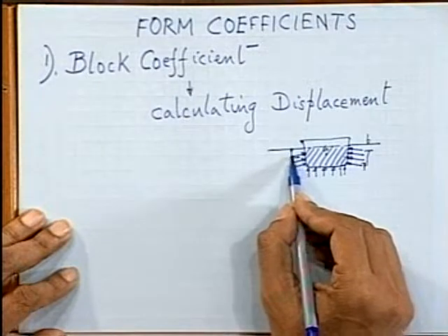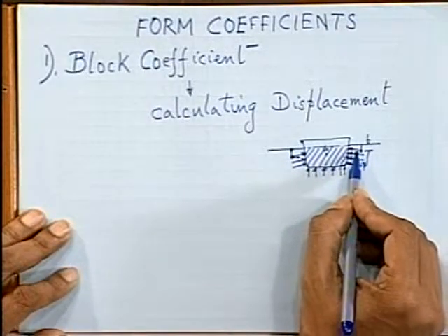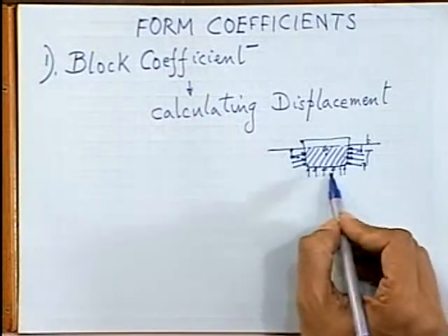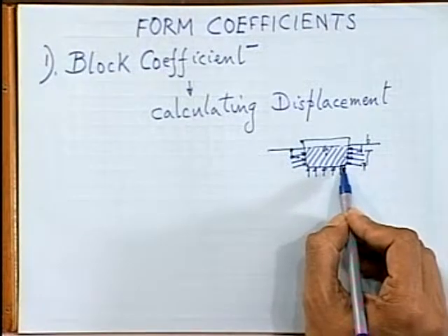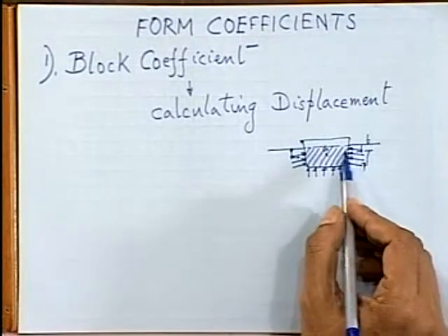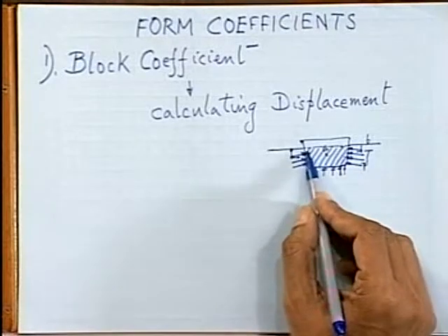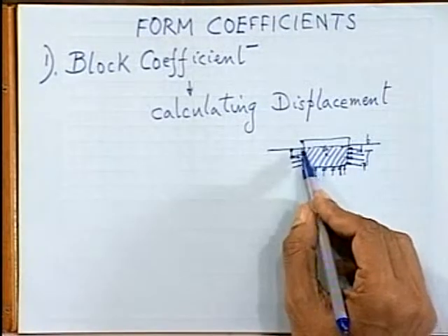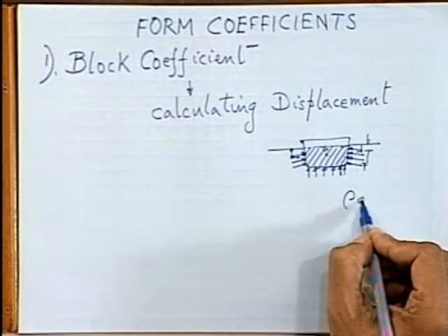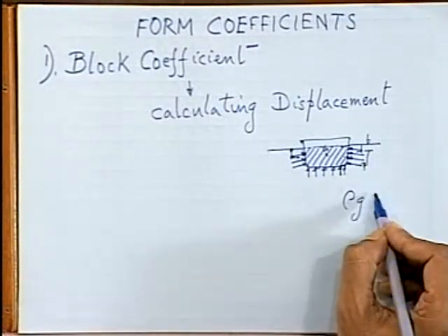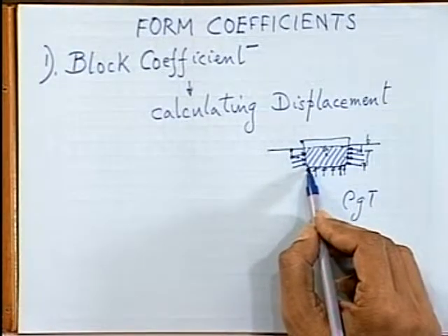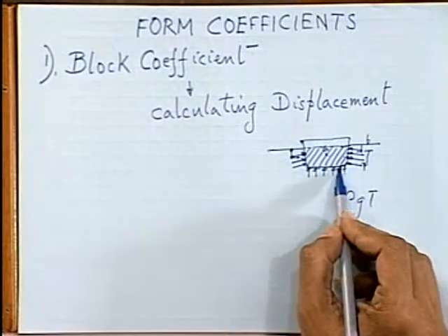Now these horizontal components will balance out on both sides of the hull, and this vertical component, along with the pressure that is acting at the bottom, will support the weight, and this weight you can find by the volume that is displaced, that will be given by rho g multiplied by draft, rho g h multiplied by the area at the base.